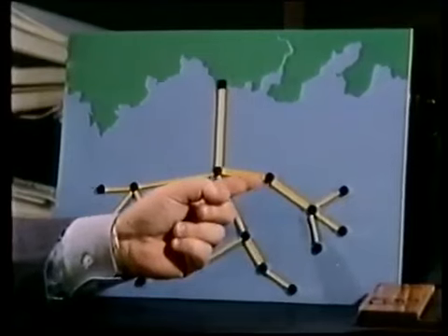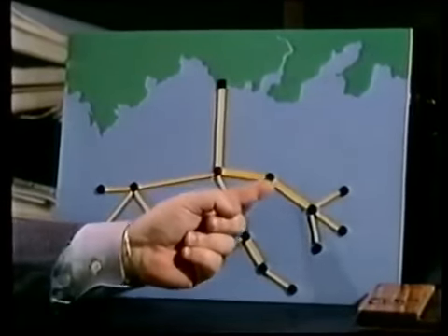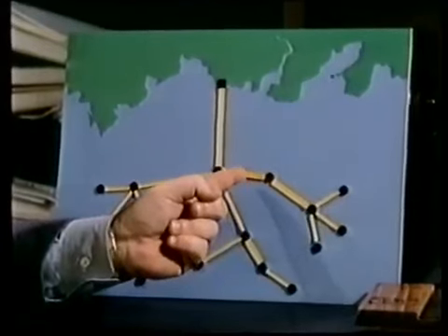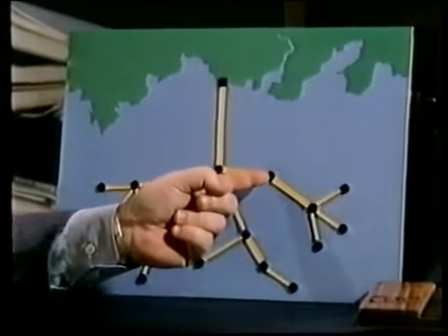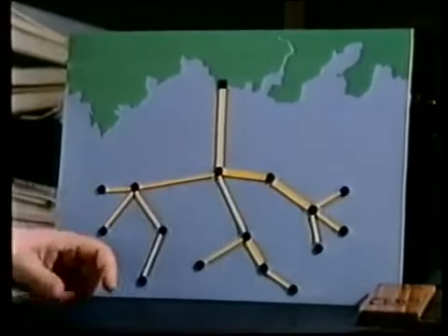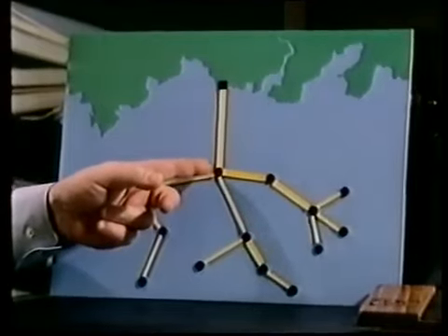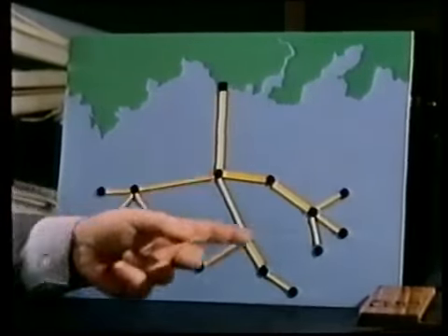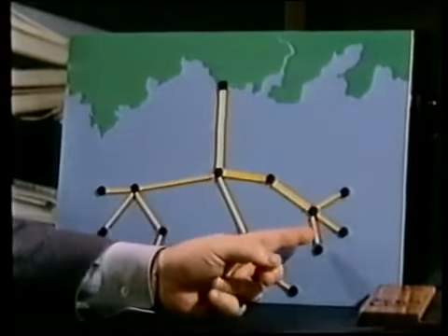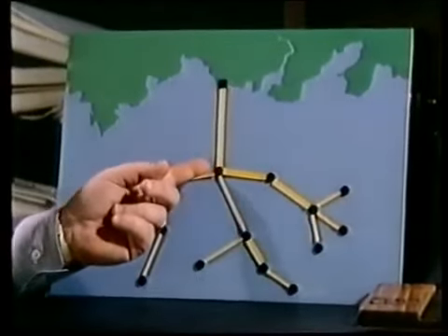We then developed a technique called a serial merge, which showed us how to collapse situations like that, that is, combine 2 branches incident to a given node into a single equivalent branch. Once we did that, we would now arrive at a node with 3 or more branches incident to them. We would then use the same technique that we developed before, called a parallel merge, to combine them again into a single branch.